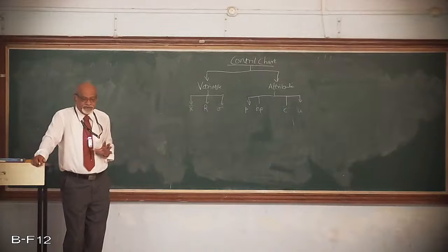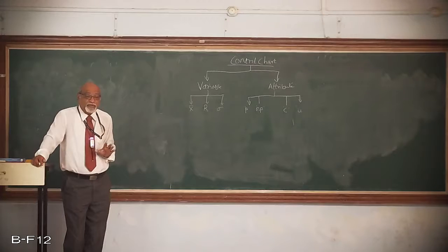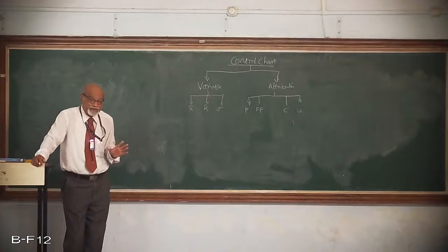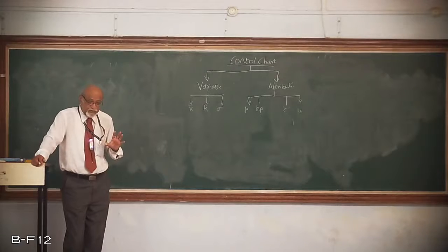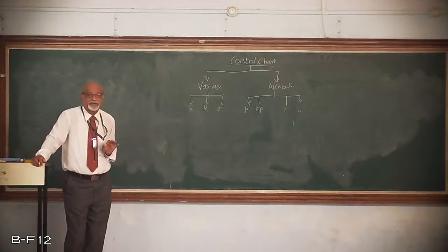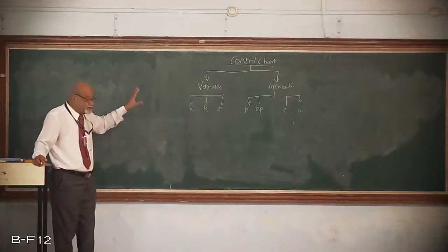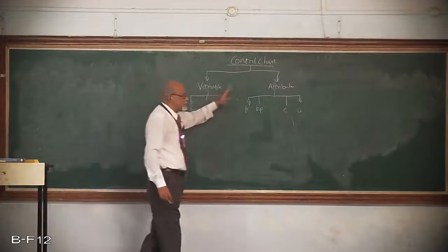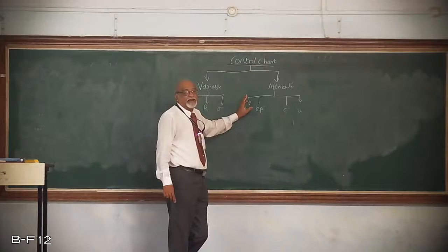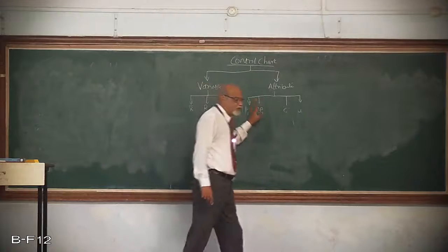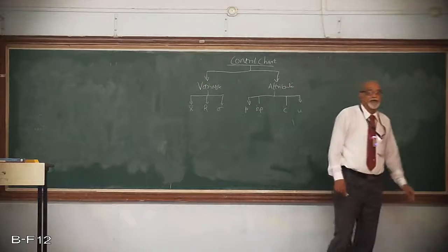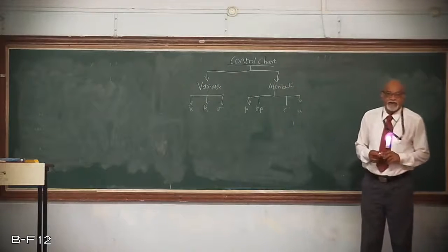One thing. Second thing is, they may not be rejected for all these 50 quality characteristics. Only a few quality characteristics are more important. That is what could be revealed by first maintaining the control charts for attributes, and then, if we want to analyze it in detail, going for the control charts for variables.